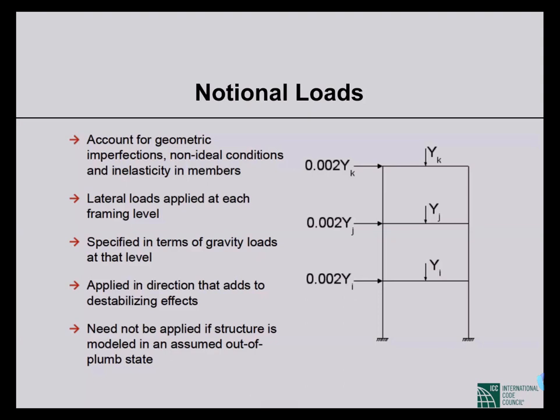Lateral loads applied at each framing level, specified in terms of gravity loads at that level, applied in the direction that adds to destabilizing effects. So we have to apply them independently in the X direction and then in the Y direction, in both directions, independently.